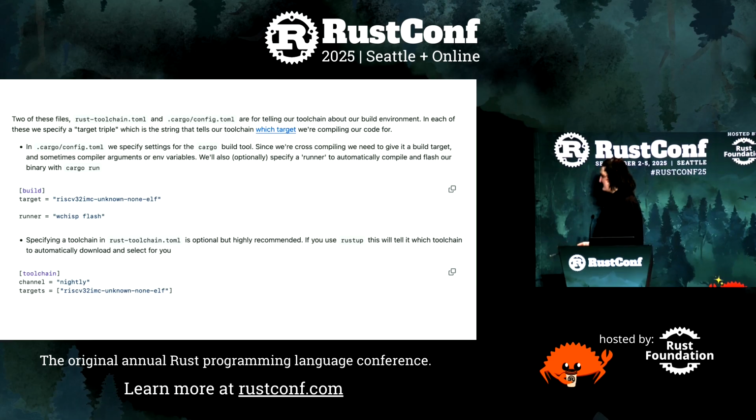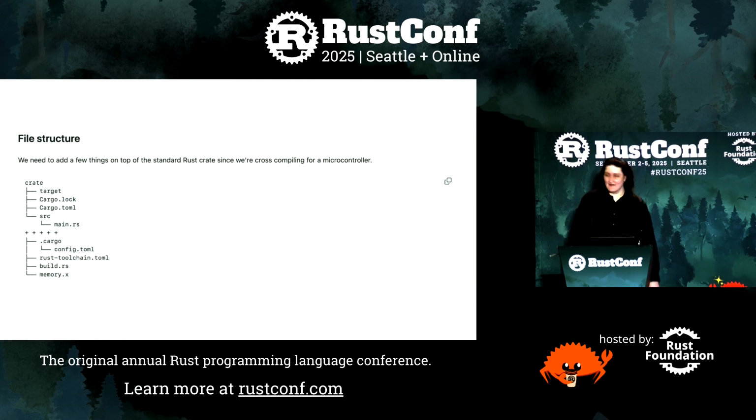And then we had to use a nightly toolchain because some of this stuff is experimental with these RISC chips. And that's not uncommon in the embedded world, having to use nightly toolchains at the moment. So this is kind of a worst case scenario for what's in one of these embedded Rust projects. I'll go back here and just mention the build script and the linker script. That's what the memory.x and build.rs are, in opposite order.